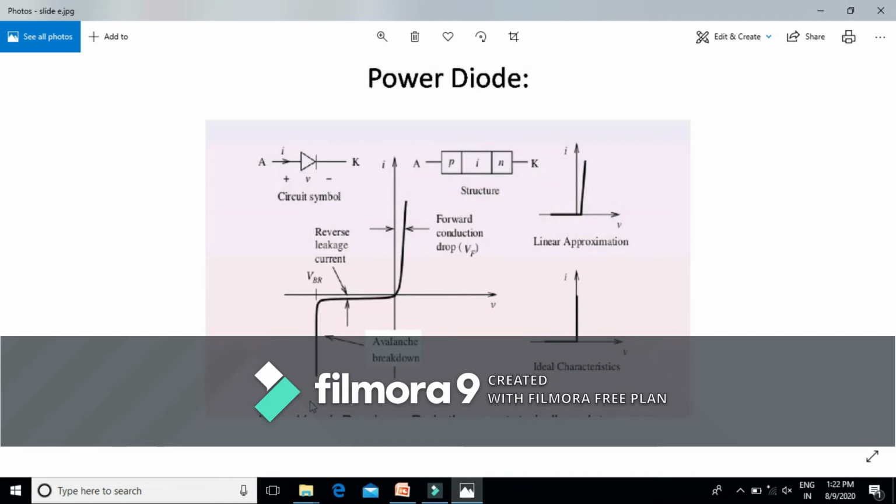It should be kept in mind that the peak inverse voltage is the largest reverse voltage which a diode may be subjected to during its working. This peak inverse voltage should be less than the breakdown voltage, else the diode junction may get destroyed, and the power losses will be very high due to the excessive heating across this junction.